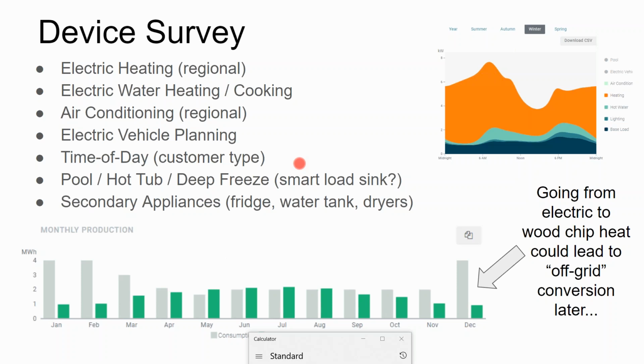And then take the bottom of the deep freeze and put in bricks. Just put bricks in the bottom of your deep freeze and put some thermal mass into that deep freeze. And so now you have half the volume, but you have two of them. And then you put them on a timer so that they only turn on during the day, and then they coast off their thermal mass the rest of the time. Instead of having one refrigerator, maybe you have a refrigerator that's smaller that you use for the day, and then a refrigerator for storage that you're not opening and shutting all the time.